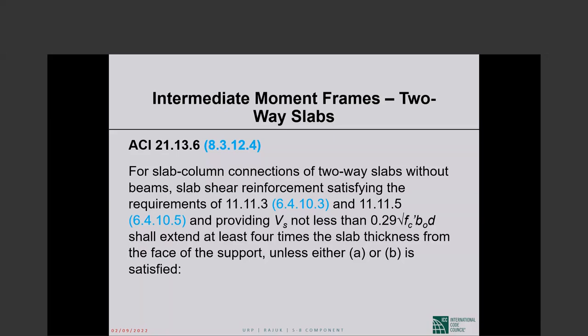which obviously had to be combined with shear walls or brace frames in California. And to the utter surprise of SEAOC and definitely my surprise, the design offices said the deformation compatibility requirements simply did not apply to slab column frames. Those were for beam column frames only. So they did not try to satisfy deformation compatibility, and the local jurisdictions, the plan check people, never said anything.